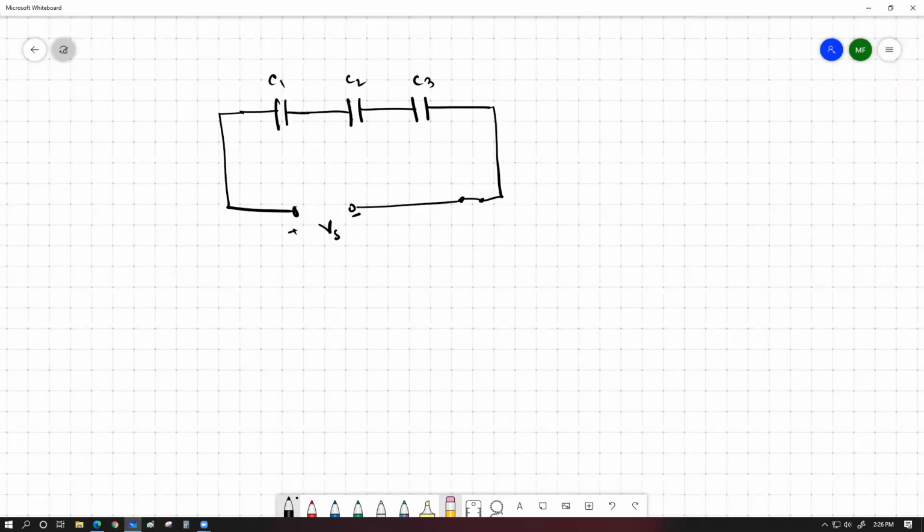And the way a battery works is that if you want to produce a current from a battery, you have to connect both of its ends with a closed circuit. If the negative plate has to give up electrons, the positive plate has to accept an equal number of electrons. There is no other way this can happen. You cannot simply take electrons out of the negative plate of a battery and not feed the positive plate an electron. The battery will simply not give you charge. You have to have both the ends connected in a closed circuit so that electrons can leave the negative plate and they can enter through the positive plate. This is always going to work that way.